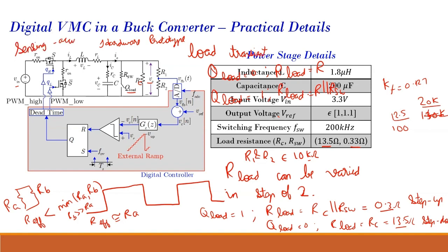These R1 and R2 resistors should have a tolerance of 1%. You choose SMD resistors with a tolerance of 1%, and that is recommended for these voltage dividers, etc.